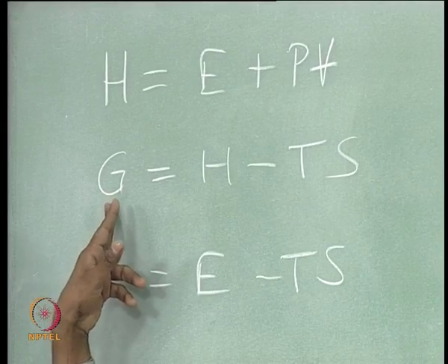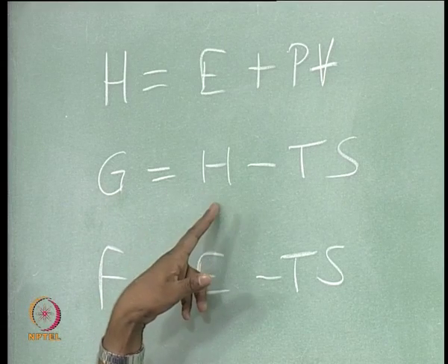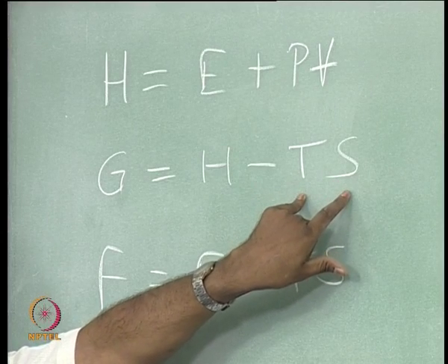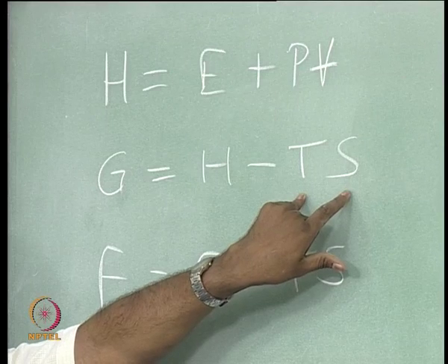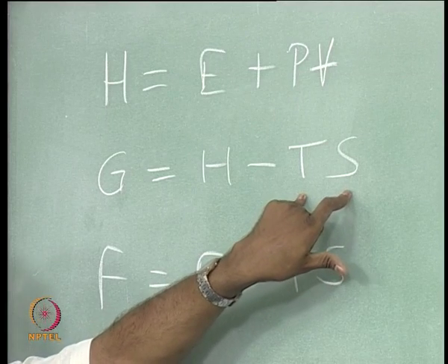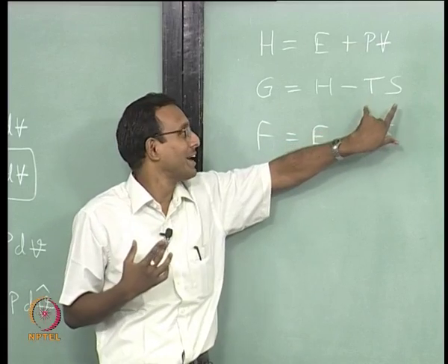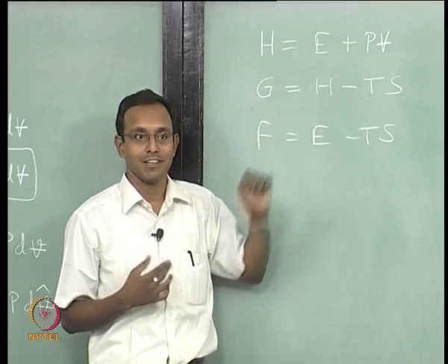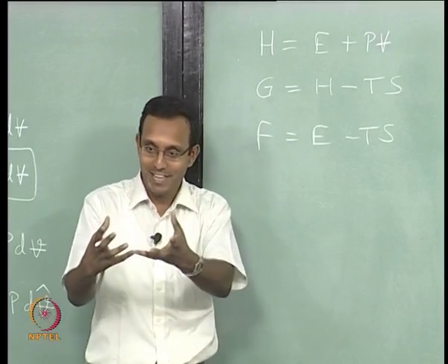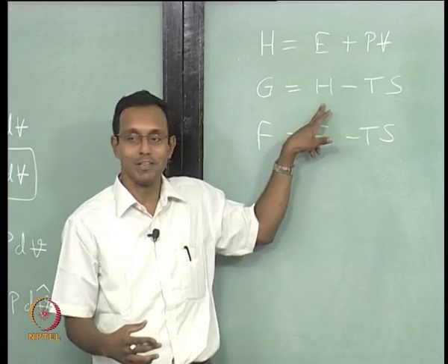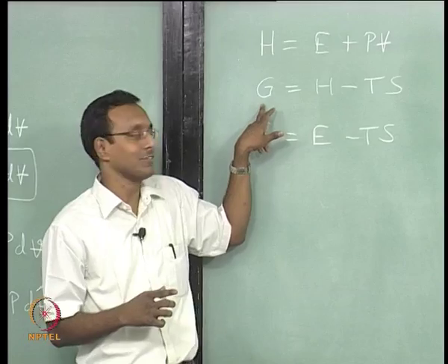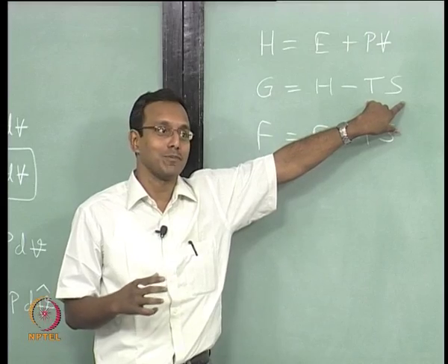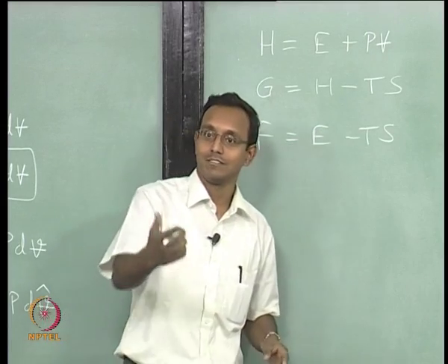If you think about it in a physical sense, what is really happening is, if I go from state 1 to state 2, I need to supply this energy, plus I have to also supply some amount of energy to increase its entropy, so that the process naturally occurs from 1 to 2. This is in a way the bribe I have to pay nature to get whatever I want happening. So, if I give the gas say 100 joules of energy, it will not give out 100 joules of energy as the work out finally. Some amount of energy will be lost in increasing the entropy of the gas.